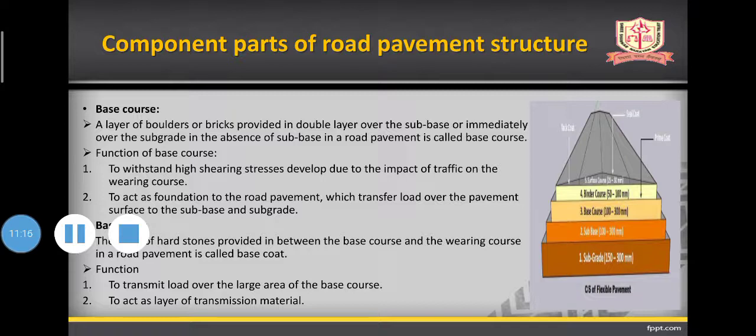What is the function of this layer? The function of the base course is to withstand the high shear stress developed due to impact of the traffic on the wearing course, and to act as a foundation to the road pavement, which transfers the load over the pavement surface to the subbase and subgrade.